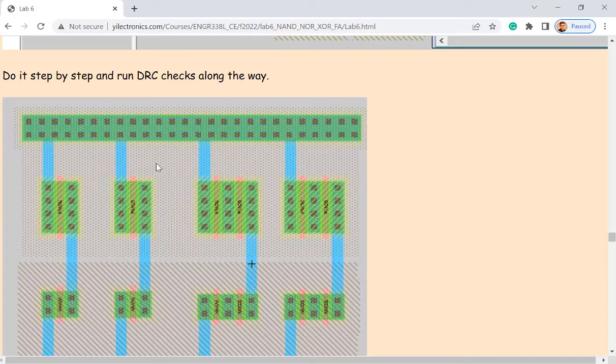You grab that one and place it in the view, and by default it's a little square. You right click and redefine the size of it and just make it big, right? And then cover it. You know what I mean? So just make it big enough. Even though you have gaps here, you have little corners, it doesn't matter because you just define the whole area and put them in the same N well. Feel free to overlap with everything here.